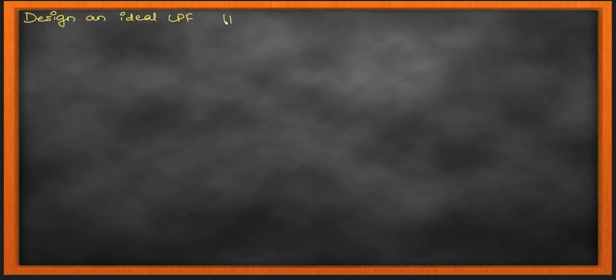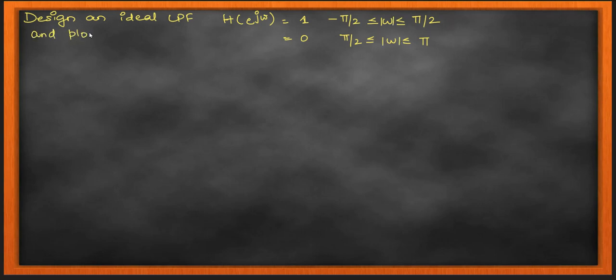So multiplying by z to the power of minus (m minus 1) by 2 is not going to alter the frequency of the signal. It's not going to affect your signals, but because your signal is being multiplied with this FIR filter, when you filter a signal, you're applying an FIR to an input signal, so it's just going to alter the phase of the signal a bit, which is acceptable by all means, because that's not going to have much effect on the quality of sound if it's a sound filter.